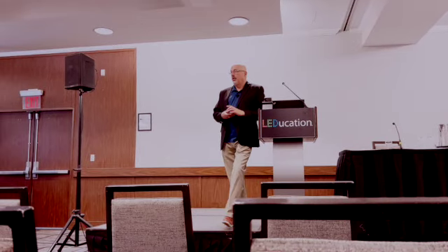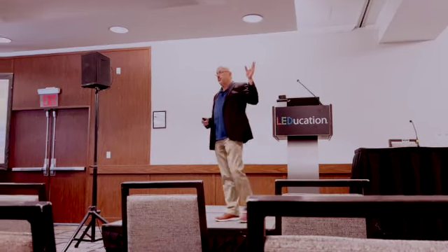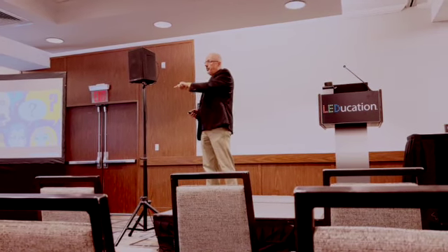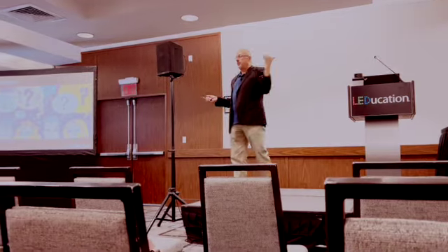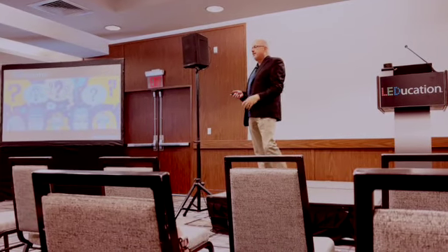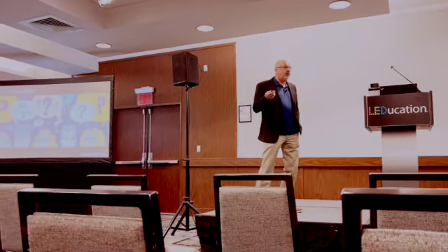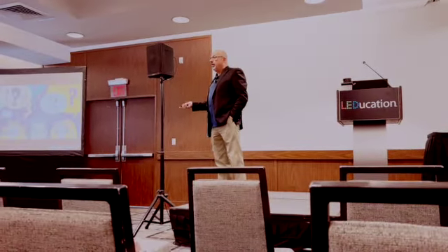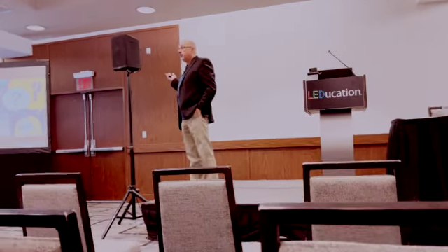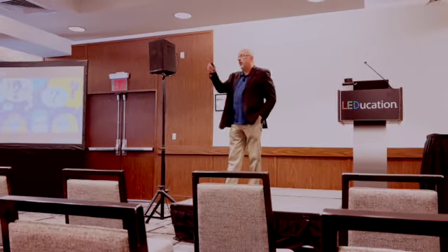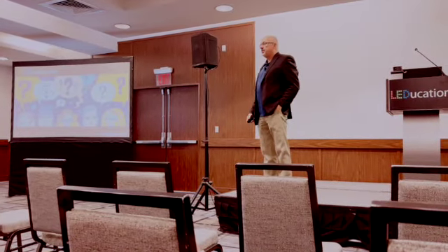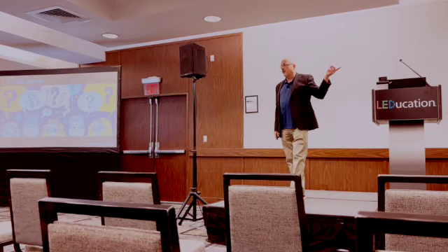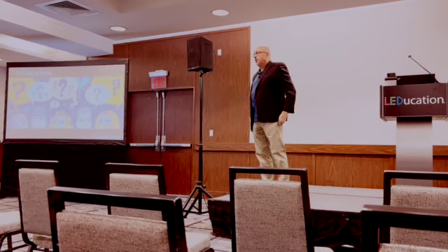Any dirty power situation, unless it's really horrific, we can handle, because we're not floating the signal on top of the sine wave. Past attempts to do this have used that type of technology. It's not even the number of buildings, it's what's going on in the building and around the buildings. Even a building like this, if they're turning their transformers on and off, or turning the lighting phase on and off during the day, that's going to send a signal that disrupts the power lines in the building to the point where it would interfere with anything floating on top of the sine wave.